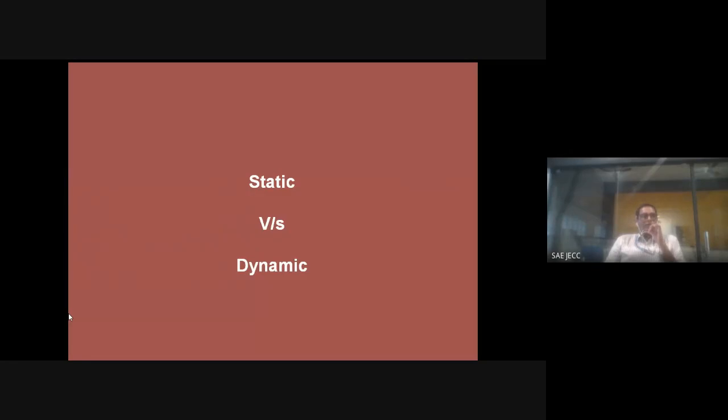One thing I want to tell you is that in many electronic equipments, the manual may say that the operating frequency should be, say, less than 40K or 50K. What do that 40K, 50K mean? The natural frequency is that particular value, and you are safe to operate the machine below that natural frequency.